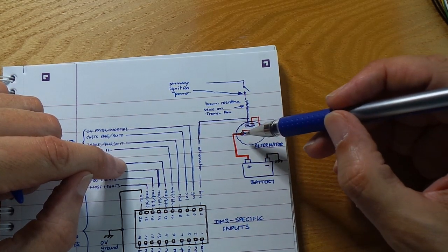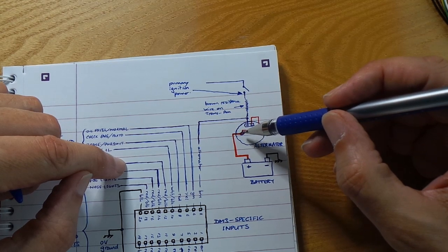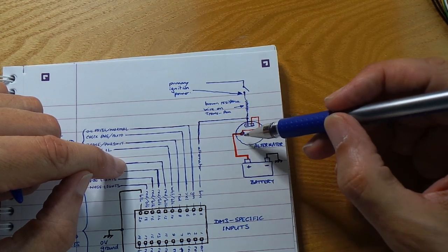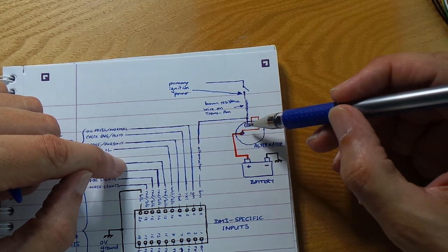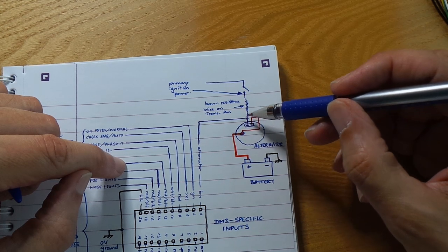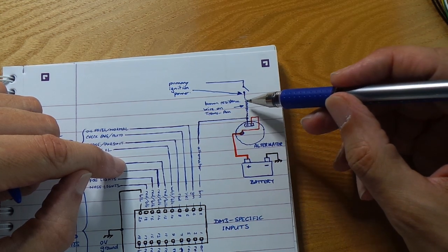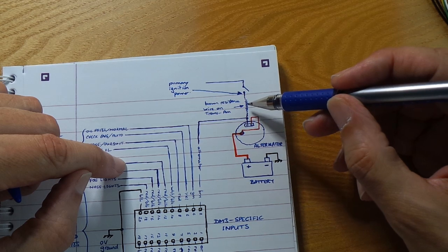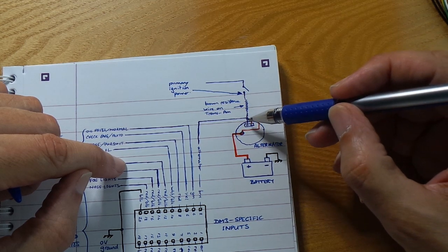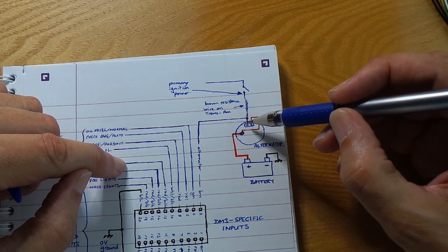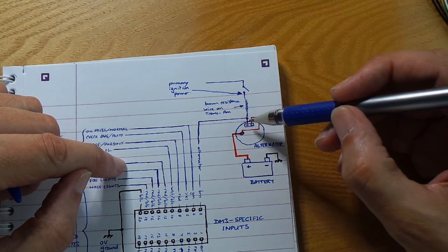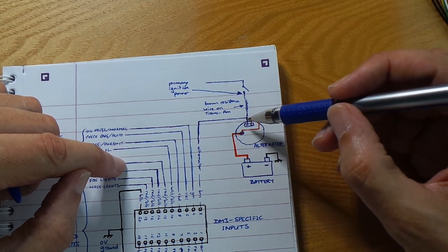You'll find that on the alternator you'll have a big output, which is the main power output, which connects to the battery, and that output will also be connected to one of the smaller terminals. Now the other terminal, which will usually go through a warning light, a charging warning light, or on the Trans Am it goes through a brown resistance wire, you'll connect this wire here to that point, and the voltage difference between the battery voltage and the voltage being generated there is an indication of whether the alternator is charging or not.